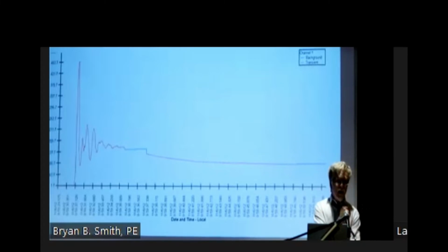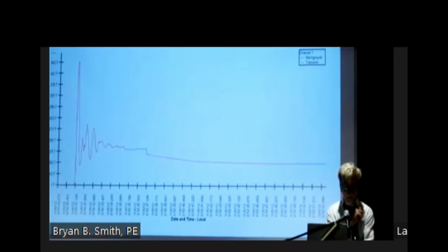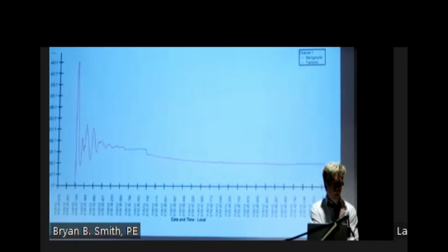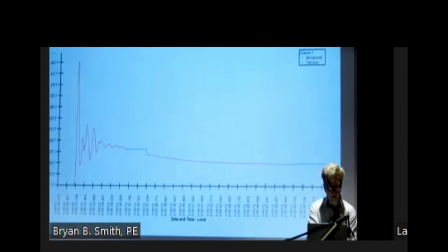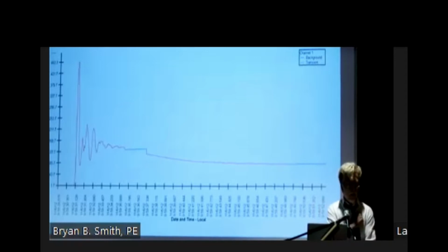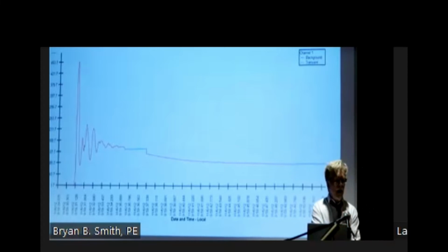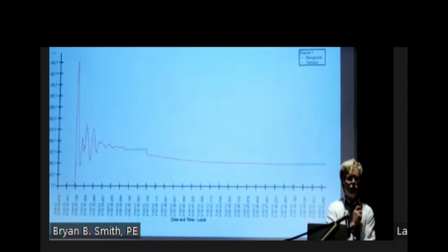So from a computer modeling standpoint, run the pump, turn off the pump, then turn the pump back on so that your supercomputer is like, okay, we're in steady state. This is good. Okay, you turned off. This change in velocity is great. We've got the inertia right in my pump. The pump curve is correct. I've got 10 points in the pump curve in here. We're fine. Here's the negative wave. The length of the pipe is this. This is beautiful. Okay, I'm off, I'm in steady state. Okay, I'm going to turn back on. So now the software is like, what's going on when I turn the pump back on? So you can look at that startup surge of the pump.